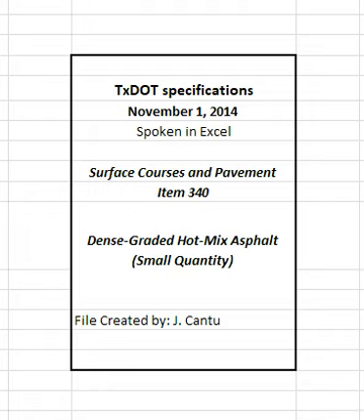4.3.1.2 Design number of gyrations, Ndesign, when the SGC is used. Design the mixture at 50 gyrations, Ndesign. Use a target laboratory molded density of 96% to design the mixture. However, adjustments can be made to the end design value as noted in Table 9. The end design level may be reduced to no less than 35 gyrations at the contractor's discretion.